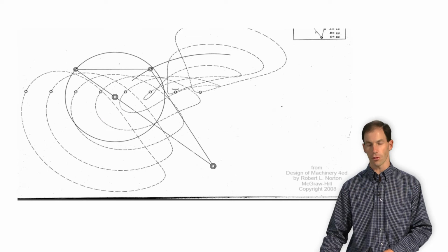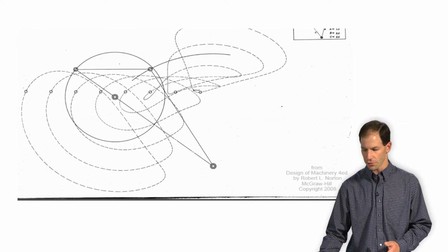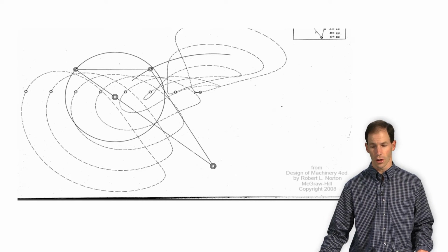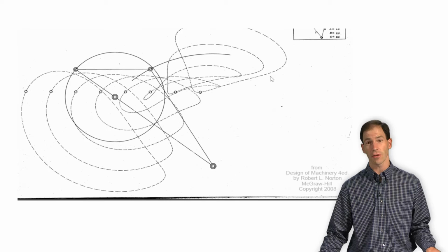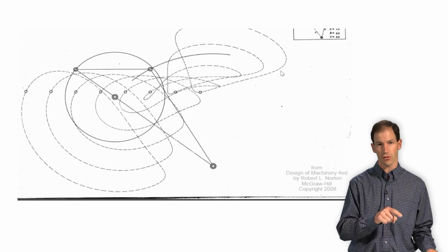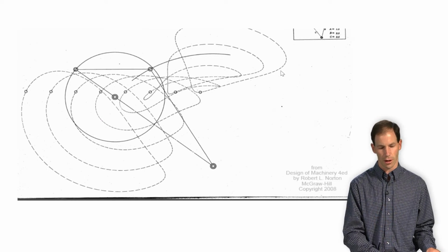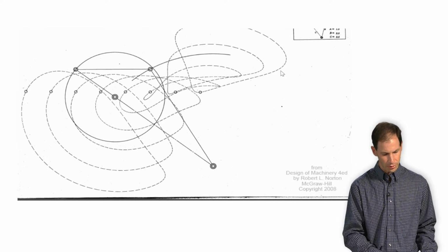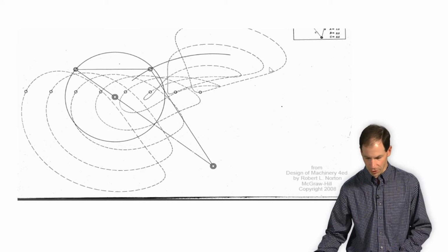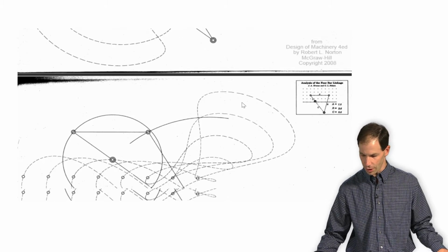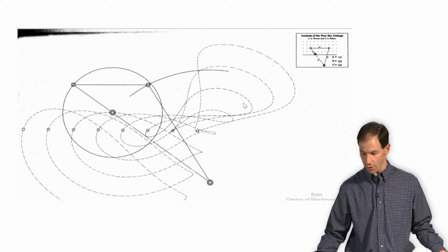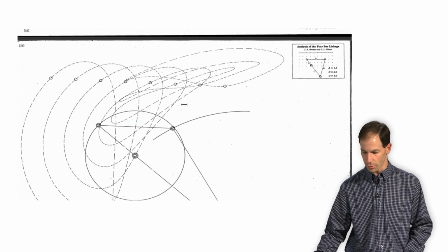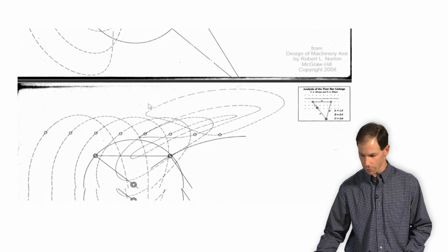And what I'm going to start to do is basically flip through the pages of this book and find where do I start to get a coupler curve that does approximately what I want it to in terms of a relatively straight line along the wall, and then a relatively straight line that's at a slight angle that dips down into my paint area of the bucket, and then repeats that process over and over again. So what I'm going to do is basically scroll through all of these pages, and I can start to see, wow, I get some variety of things where I get some loops in here. I can perhaps get some other behavior that is quite complex.